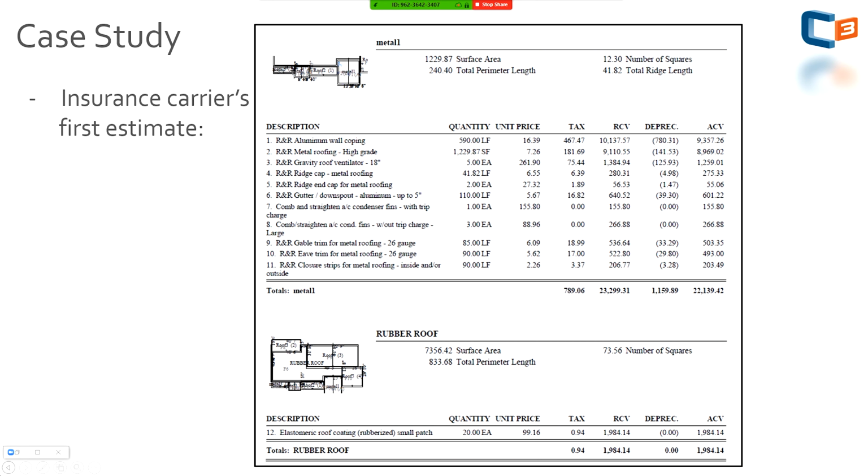So we looked at the insurance carriers' assessment. This is very common with commercial adjusters. They know sloped roofing, they know shingles. Anyone can walk up on a shingled roof or even a mod bit roof and say, oh, granule loss, bruising, got it, hail. But on EPDM, it's different, and you could tell the lack of knowledge on the insurance adjuster's side on this.